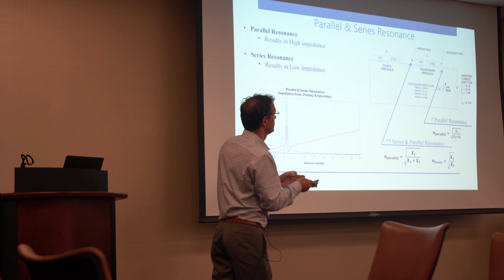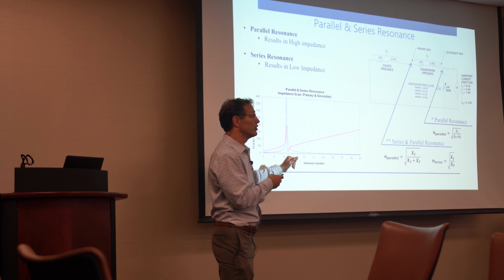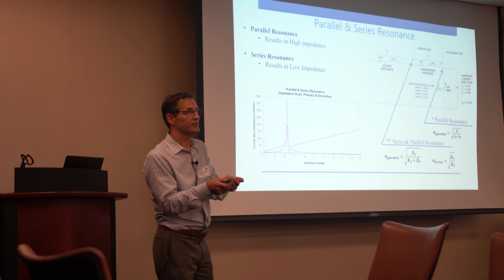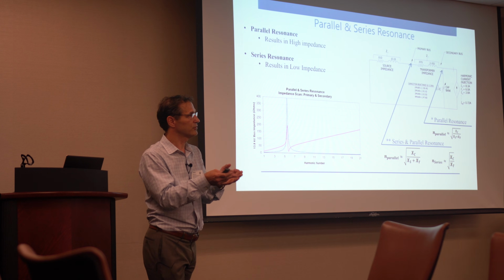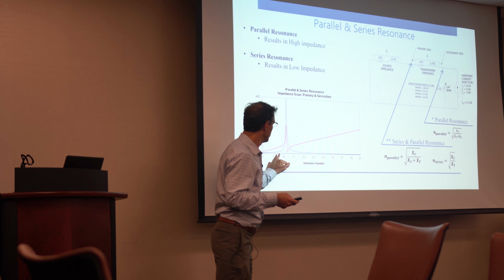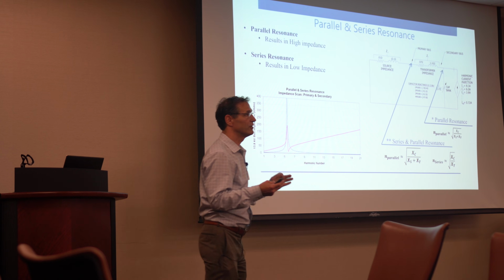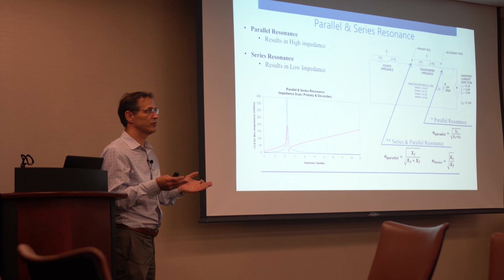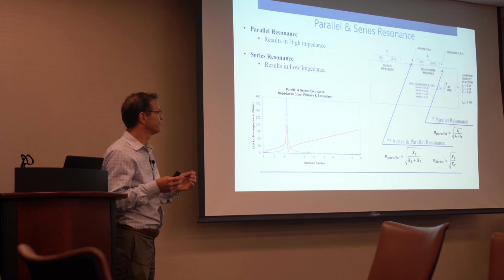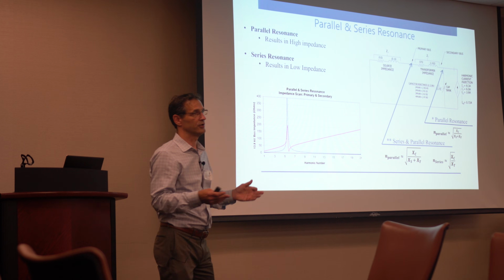The more you add, the more it shifts to the left. Key point: when you do power factor correction, it tends to be that networks have a certain impedance, and by the time you get done correcting power factor, you're going to end up with a resonance between the 5th and, say, the 8th. If you have a requirement to correct power factor to near unity, invariably the resonant point comes down to that lower frequency, and it becomes a concern.